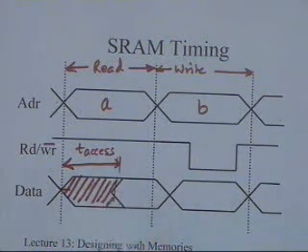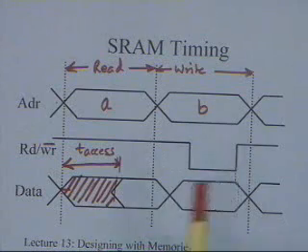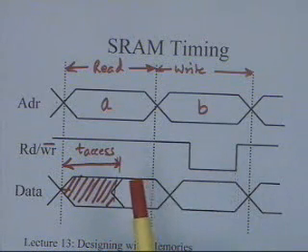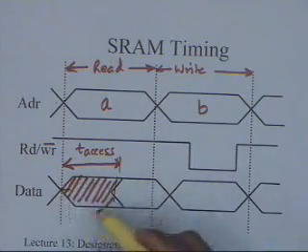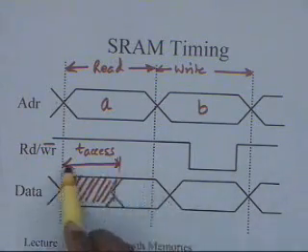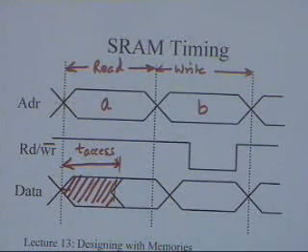That means when I say that I have a RAM device which has an access time of 60 nanoseconds, in 60 nanoseconds the output will appear. It can of course appear earlier, it can even appear after 3 nanoseconds. There could be a lot of variation. So during this period I cannot trust the output, but after I wait 60 nanoseconds after the address has changed, I am sure that my output corresponds to the address that I am reading.